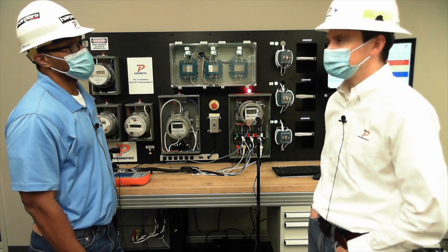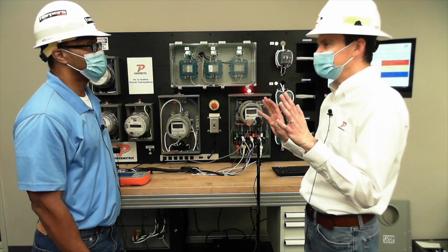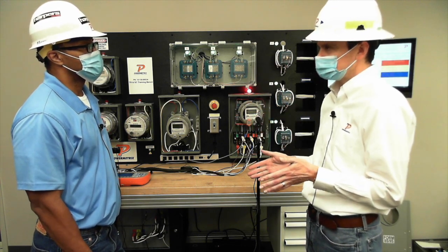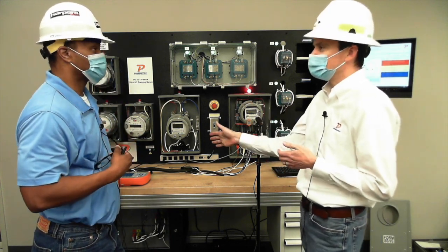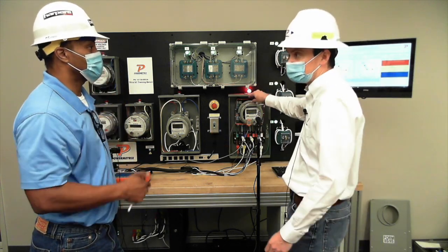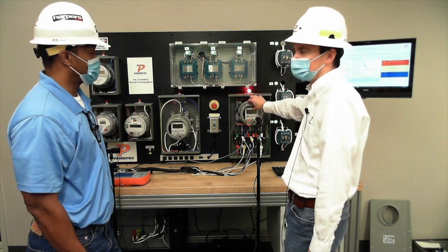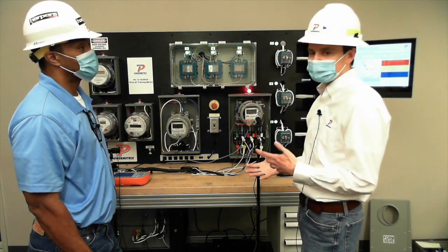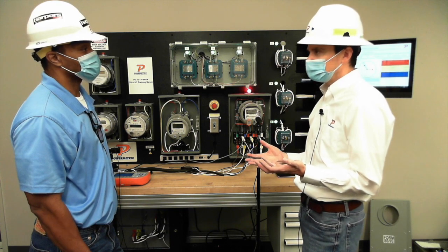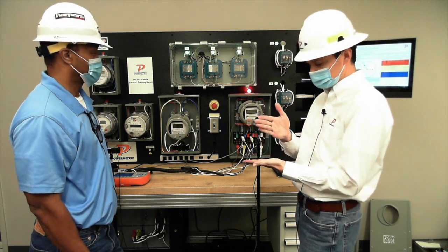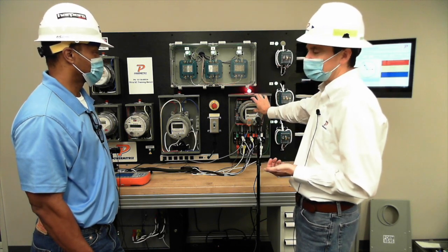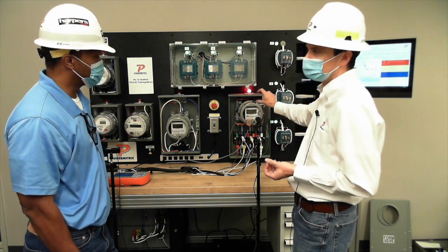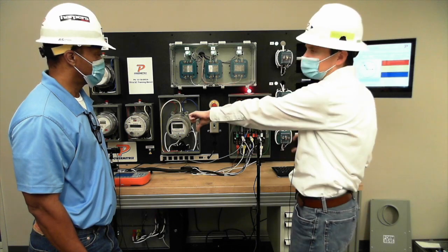Yeah, so the reason why we want to, even though we're a big proponent of customer load testing, I understand if you run a demand test and the test is over, you're going to look up pretty quick to see what the register is so you can compare the difference. Exactly. Now, if you had a load box and everything's simulated, it starts and stops at the exact same time. That way the meter is dead and you can verify that the registration, the kW read is the same as what's on the PowerMaster.